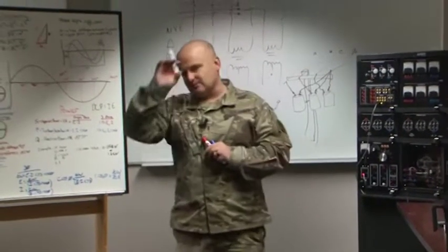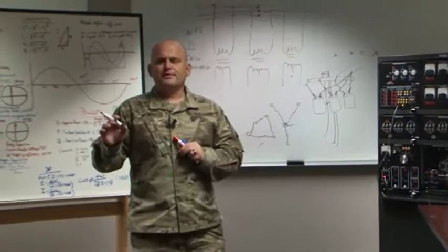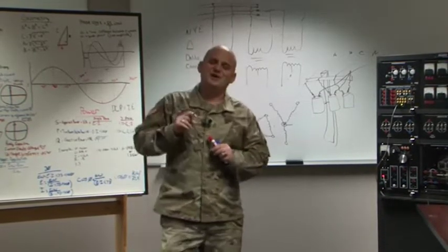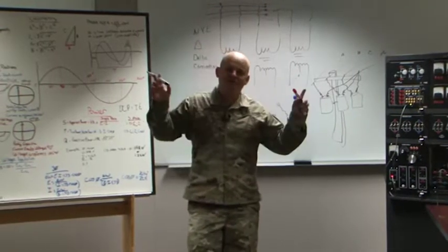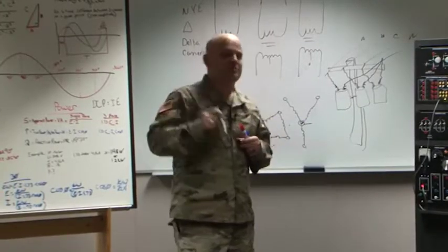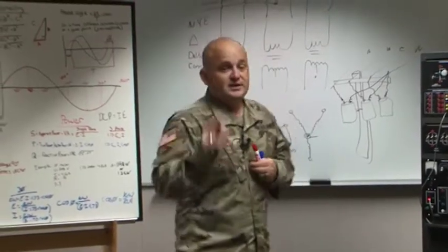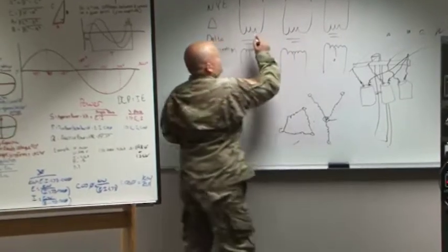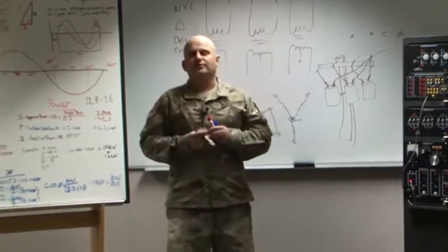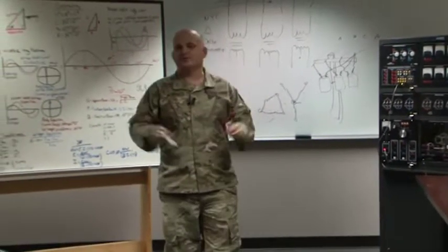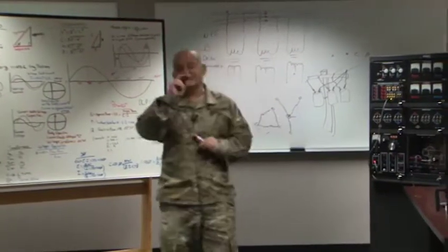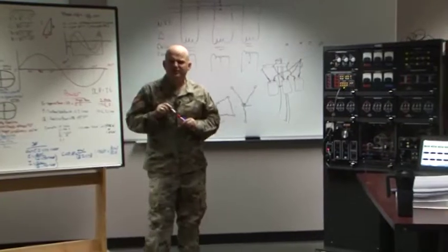I don't want to get into some deep, dark vector logic here. However, that 30 degree phase shift between 120 degree references, which is your voltage, is what the deep dark science goes back to, why 1.73 is a factor in your resultant. It's going to cause you to have current and voltage differences depending on your connections that are scaled by the square root of 3. All right, you're going to do it in the lab. Just know when you read about that 30 degree phase shift, it goes back to unit 6 when I explained to you the origins of 1.73.